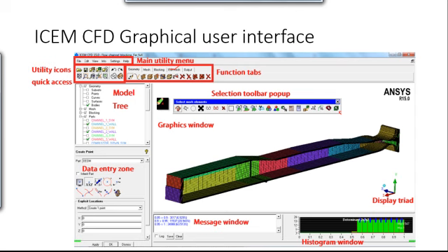You can extend your mesh, you can revolve your mesh, and also you can process the prism meshing. You can increase the number of layers inside the prism mesh. You can also change the distance of the first cell from the wall of the prism mesh. You can also change the ratio of how they grow from one layer to another layer. All you get inside the edit mesh menu.